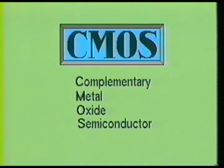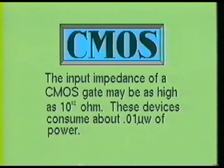Another commonly found logic family is the CMOS family. CMOS ICs are constructed with complementary metal oxide semiconductor devices. The insulated gate in the CMOS device provides a very high input impedance. This causes the device to consume very small amounts of power. The power consumed by a typical CMOS gate will be about 0.01 microwatts. This makes the CMOS logic family ideally suited for battery-operated circuits.